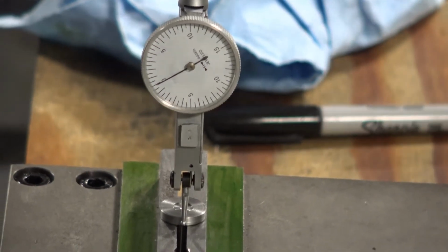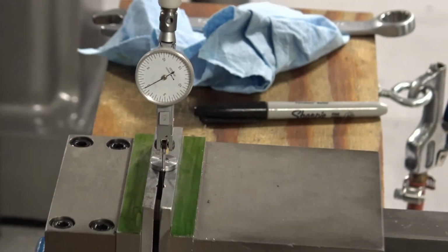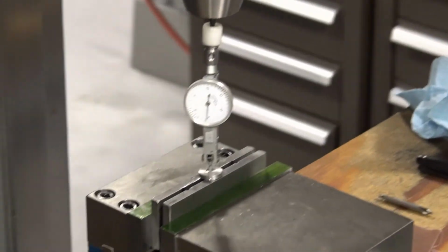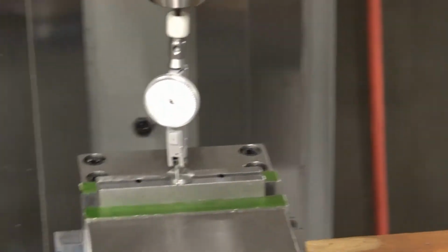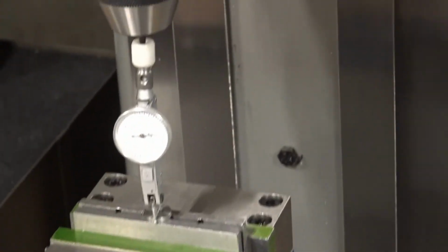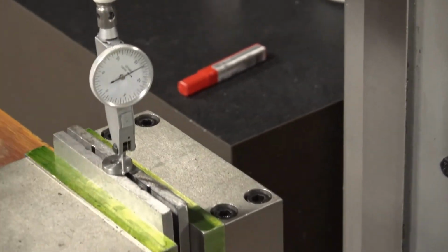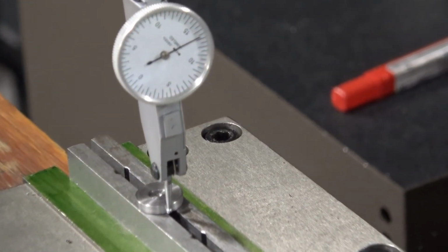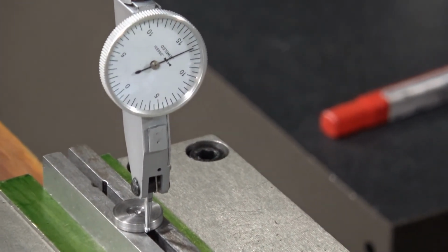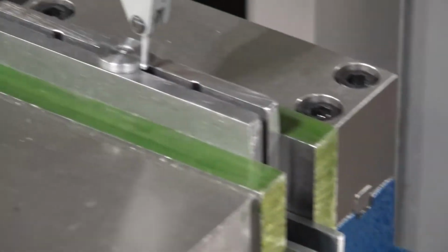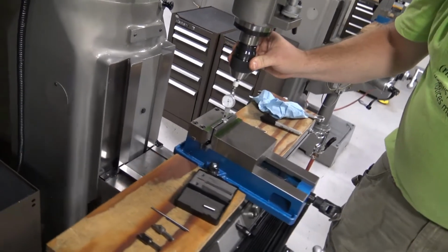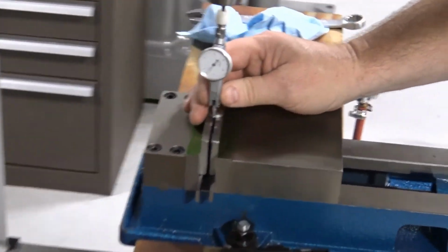So now my next step is going to be to rotate the spindle 180 degrees. Now it's going to be important for you to watch which direction that needle rotates. And you can see that it actually stopped moving, right? Well, it stopped moving because it actually came off of the workpiece. So we're going to go back. I'm going to make a little adjustment here. All I did was move it about 5 thousandths. We're going to go back to the front side, and I'm going to put the preload back to 0.